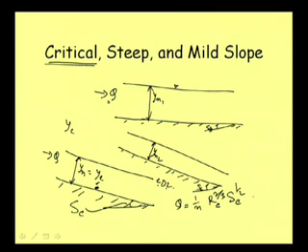Of course, we have written this velocity expression, and it must be multiplied by the area to get the Q. So, it is also A C. Area is also a function of y, so this A C means the area at the critical depth. So, with this expression we can find out what our S C is.